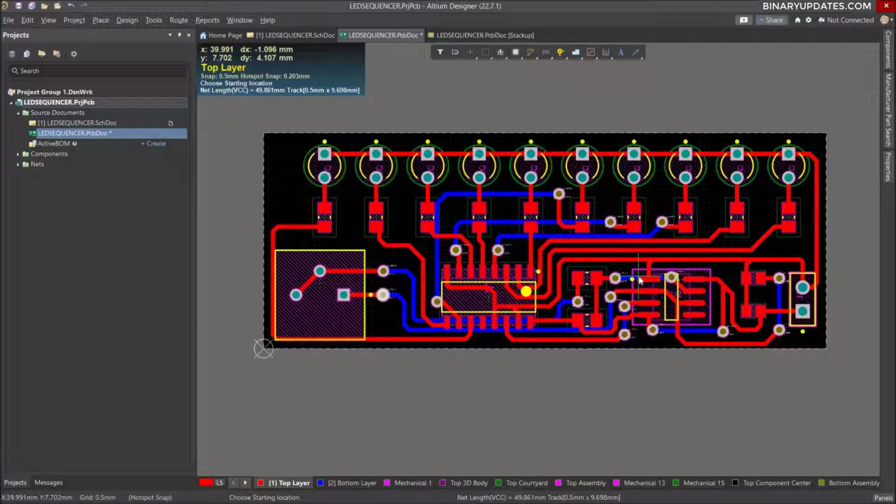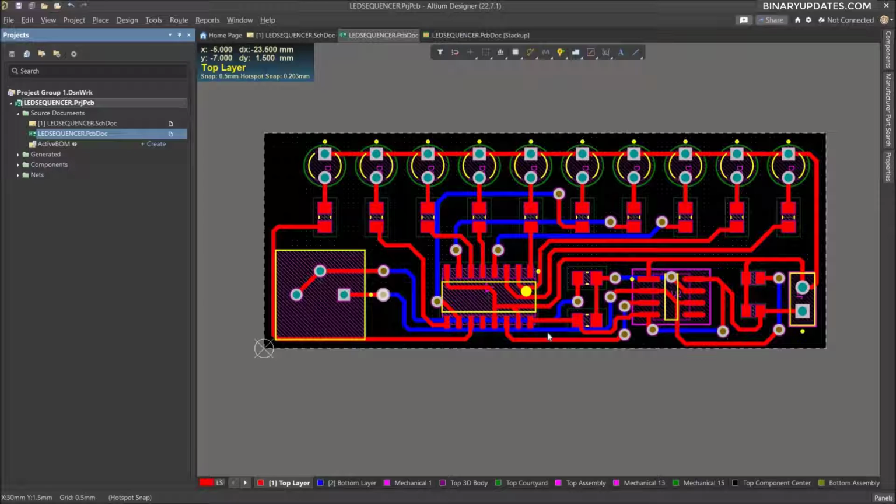You can download that and study the tracks that I have drawn, and then you can draw the tracks accordingly. So now we have finished a complete routing of a PCB here with all the components. So it's very important for us to check whether there are any possible errors or some unconnected route paths or something like that. Any error or potential warning, before we do any further optimization or generate Gerber files, we have to make sure there's no error of that sort.